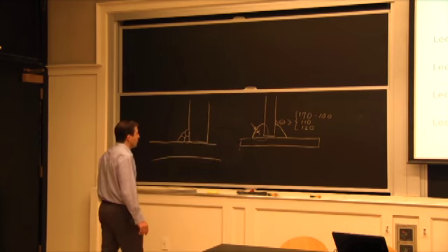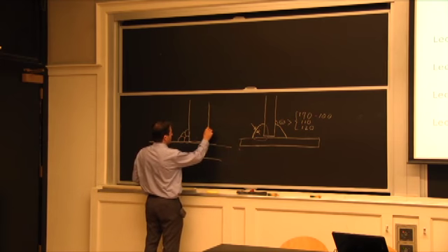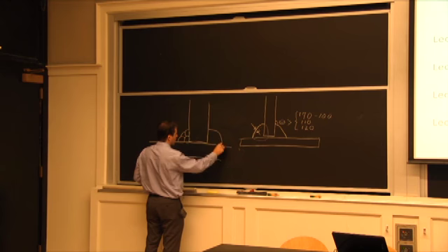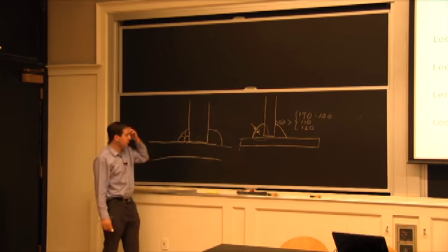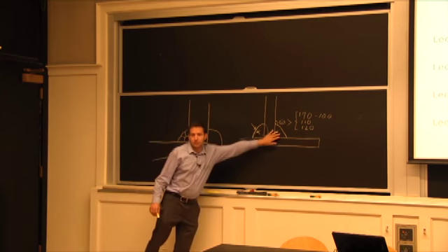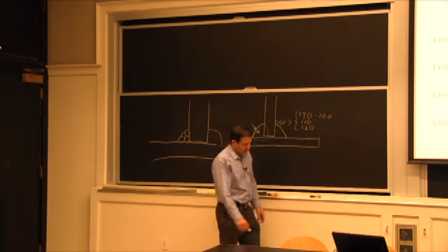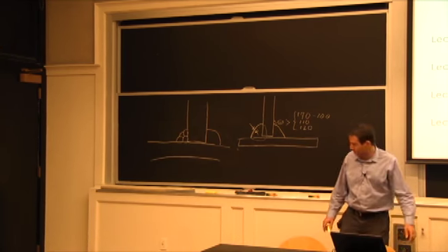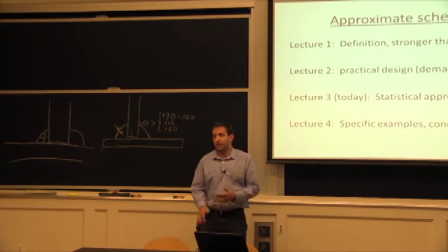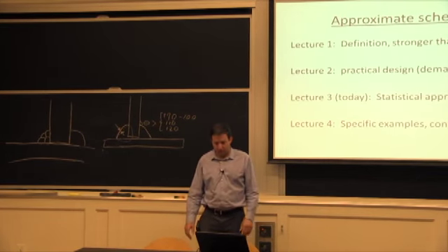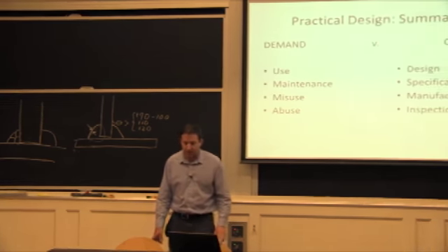So now you know when I say not fully fused, that's what I mean. I mean a bead that's going to be more like a caulking joint here in the corner as opposed to being flatter like this one. And it's all based on the fusion. So the inspector needs to be told or needs to know what's acceptable and not acceptable in addition to being there. So we have a lot of different things that ties into the factor of safety.